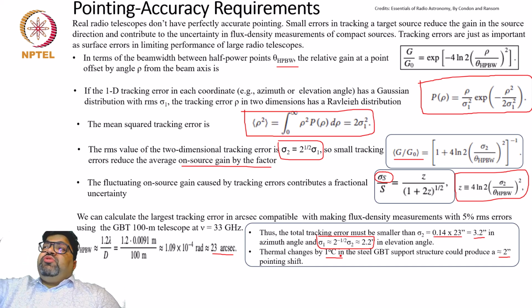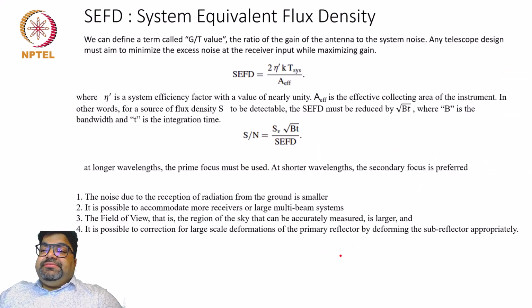So you need to focus on a known source, see how off that is from the center, because sources have a structure, and so does the far field power pattern, and so they have to be deconvolved out, and understand whether it is pointing at the right place at the right time, or if it is not, then correct for the model from the observation, and then you reduce this error.